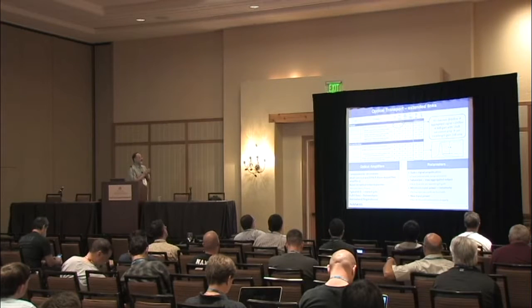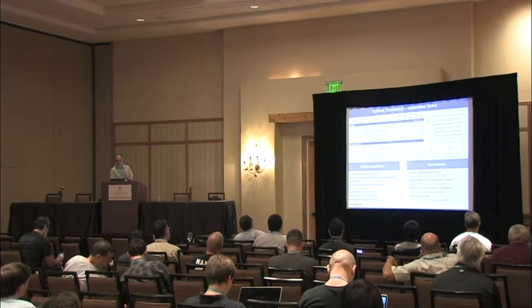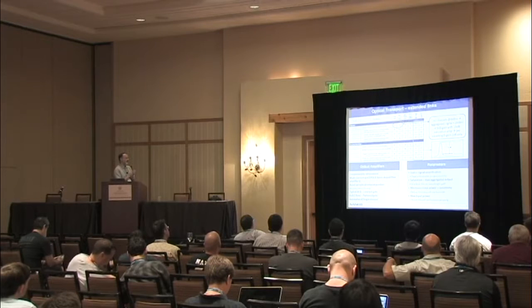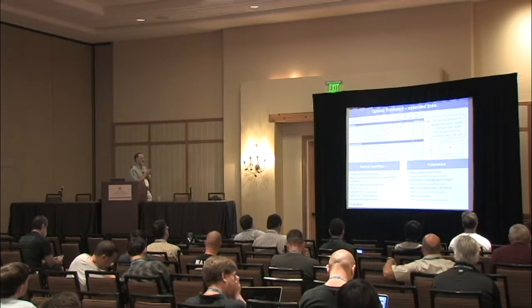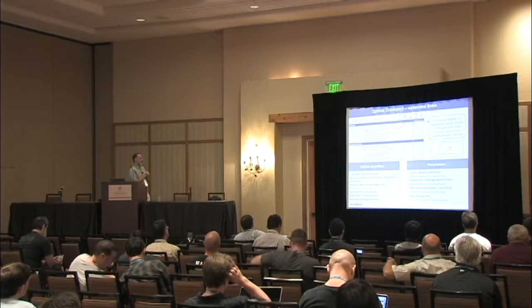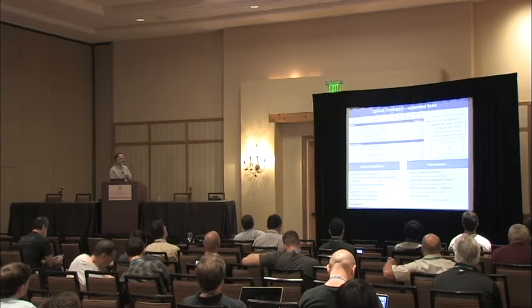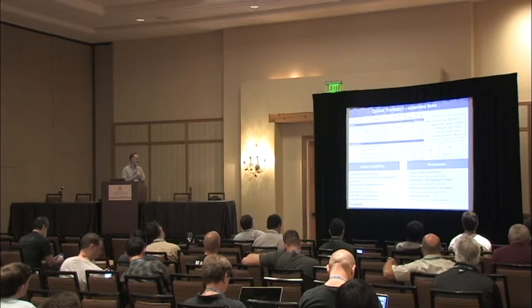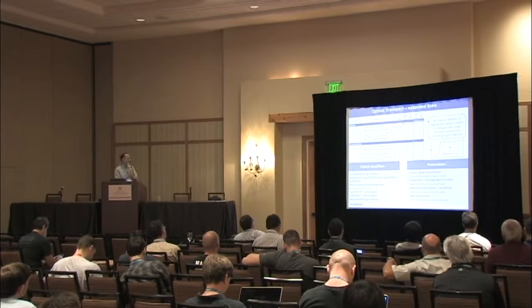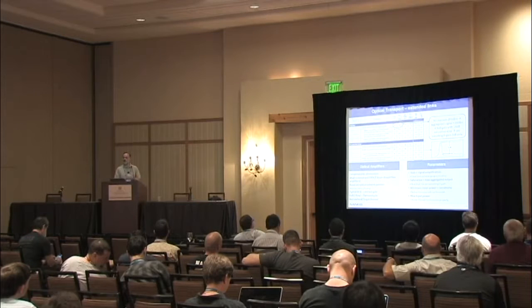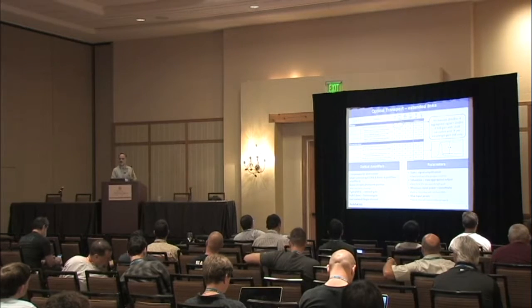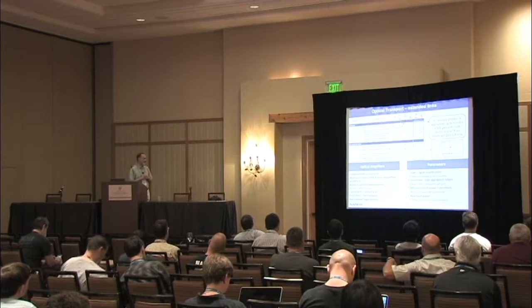About amplifiers, we put some amplifiers here as examples, and we are going to look at different parameters. The most common in the industry are EDFAs, erbium doped fiber amplifiers, and based on the position in the network, in the link, you are going to have boosters, inline, preamp. We talked about this. Typically, it's in automatic gain control. The gain is always fixed. The amplifier tries all the time to get you that gain.